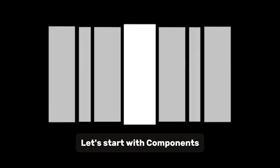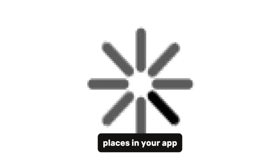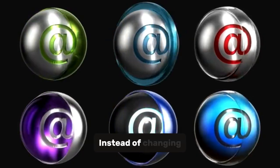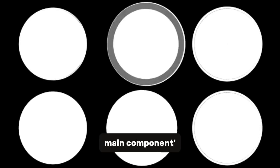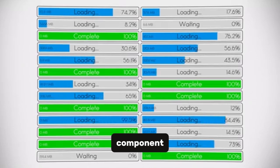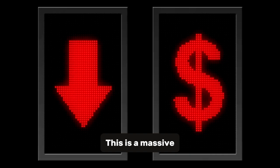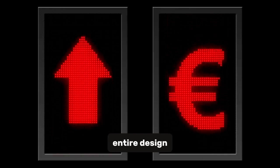Let's start with components. Imagine you designed a button that you need to use in 20 different places in your app. What if you need to change its color later? Instead of changing all 20 buttons one by one, you can create a main component. Then, you create instances or copies of that component. When you edit the main component, every single instance updates automatically. This is a massive time saver and ensures consistency across your entire design.